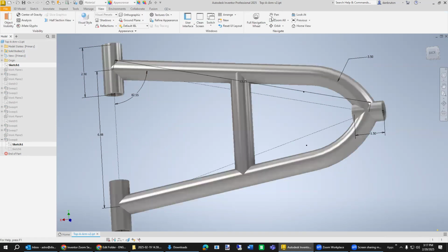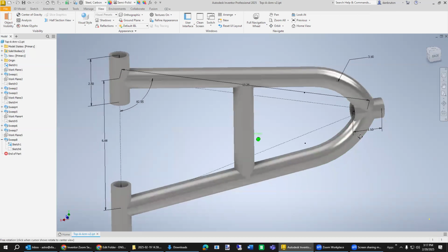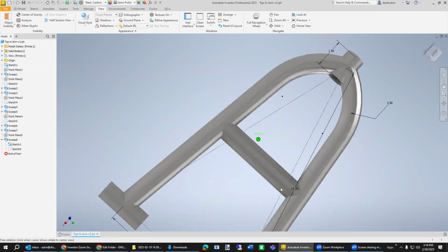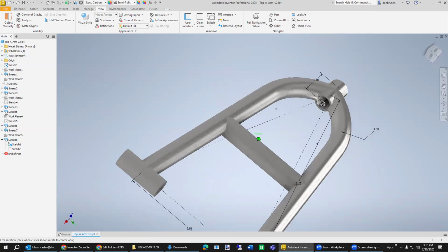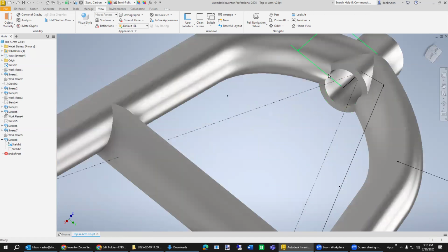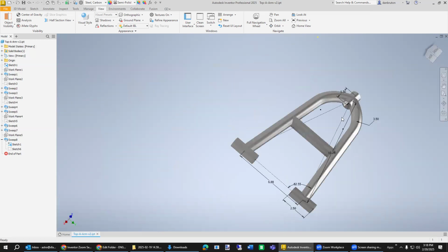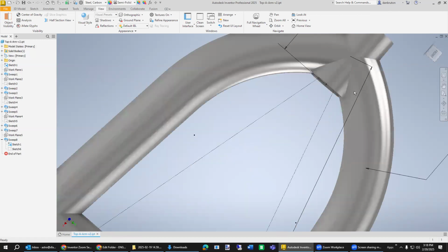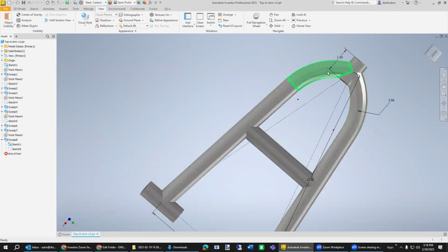If we make that change and move it forward, though, it looks like there's a little bit of an issue. Let's see if we can find it. A little bit of an issue right here. See that overlap? We don't really want it to do that. That just means that we don't want this line that is 1.5 inches in length to be at the midpoint. We need to shift it down this way a little bit to handle the angle coming in. So maybe we can shift that down maybe 1/4 inch if we're lucky, removing some of our constraints.